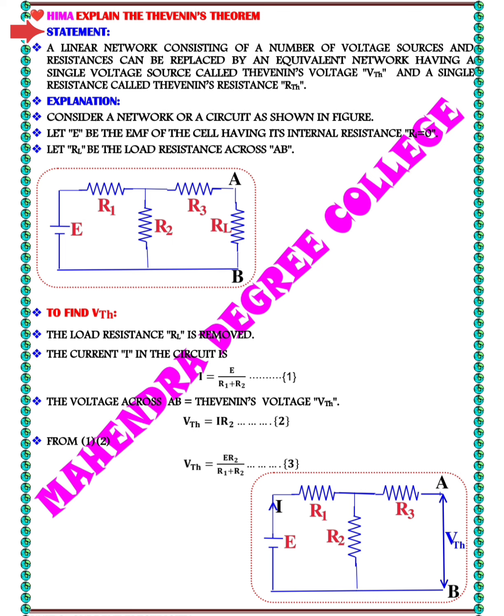First of all, we look at the statement of Thevenin's theorem. Thevenin's theorem states that a linear network consisting of a number of voltage sources and resistances can be replaced by an equivalent network having a single voltage source called Thevenin's voltage, V_TH, and a single resistance called Thevenin's resistance, R_TH.